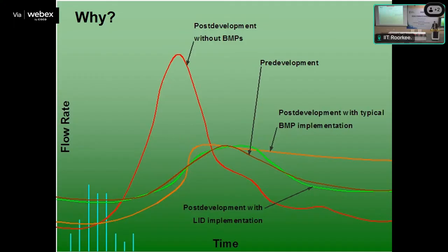Yesterday, the professor talked about how in Bangalore, which is obviously in the south, they had added 100 square kilometers of city in the last decade. That's a lot. So they're knocking out vegetated areas and replacing them with impermeable surfaces. All right. Well, what hydrograph do you get when you knock all the vegetation out and you put up impermeable surfaces? What color? The red one.